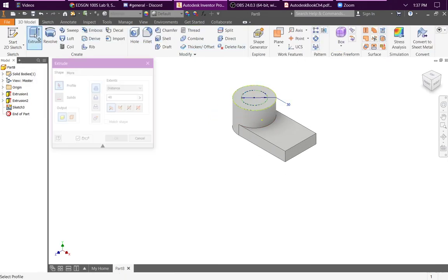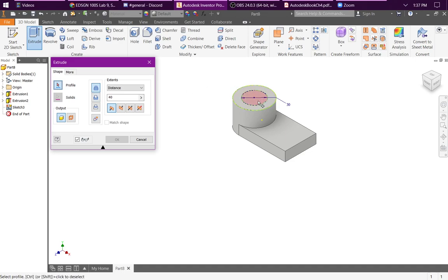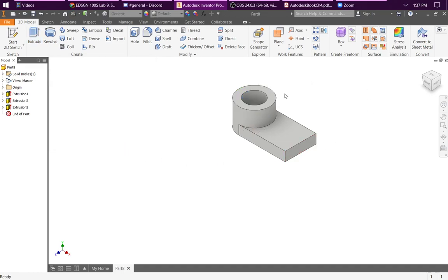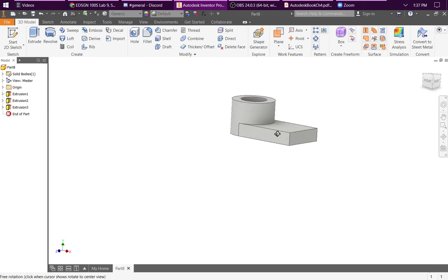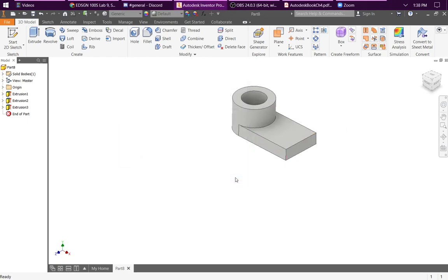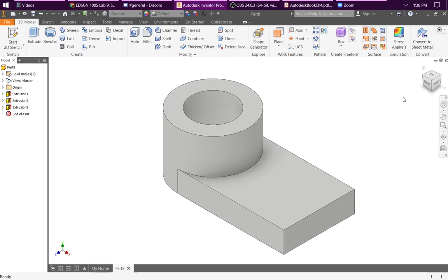click on that sketch and hit extrude, choose the area that we want to make our hole out of, and it keeps giving us the opposite direction that we want, but we can always switch the direction. And now it has automatically changed it to a cut, which is good. And instead of the distance, let's make this go through all. That way if we ever change anything, the hole always still go all the way through. Then click OK or hit enter, and we can see we've got a hole through there. And if you hit F6, it'll bring you back to the home, or click up here for the home button.